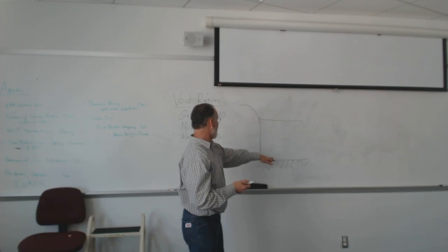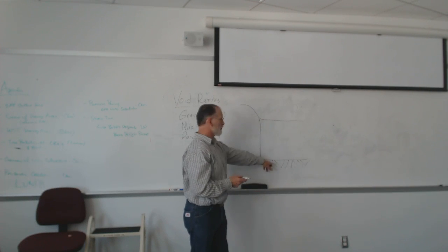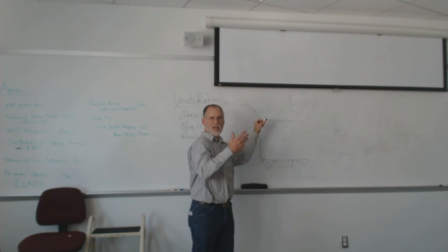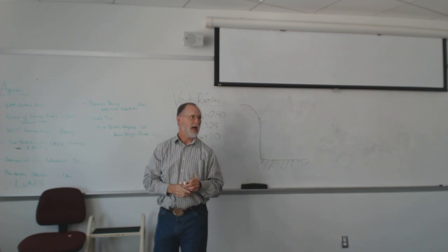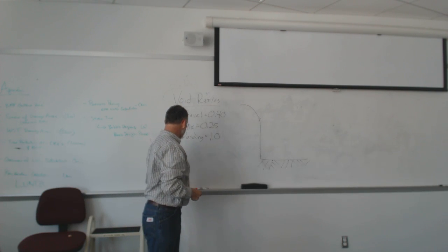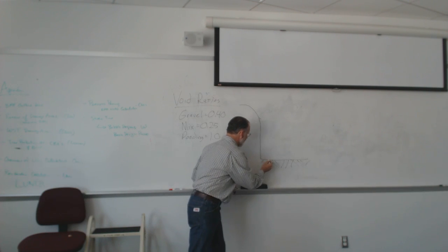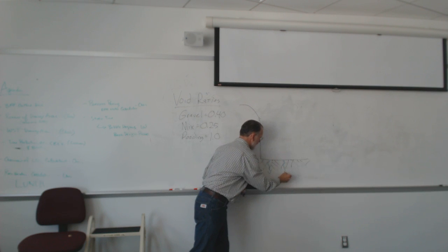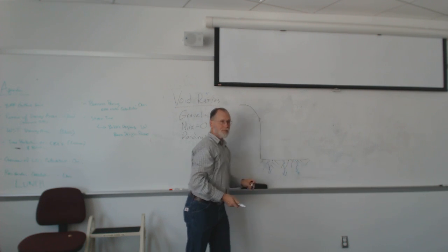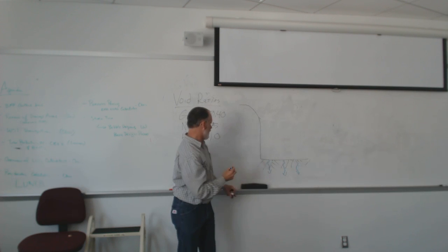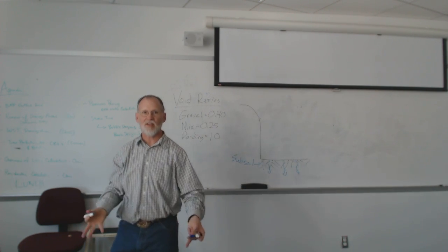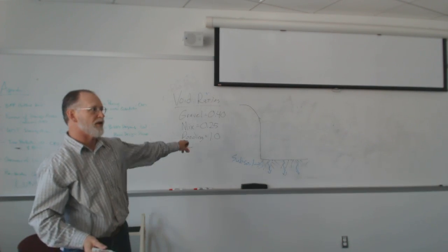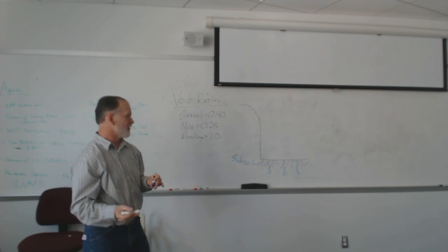So when you're excavating out the rain garden here, this is where our infiltration is going to take place. We dig a hole. Right now we haven't put anything in there, right? We dug our big hole, but when it rains and this hole fills up with water, this is where our infiltration is going to take place. These are what we will call subsoils. The stuff we pull out is soil. The stuff that's left, the dirt you see at the bottom of the hole, we call subsoil. That's where our infiltration takes place.